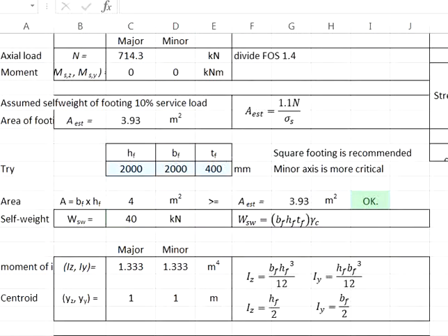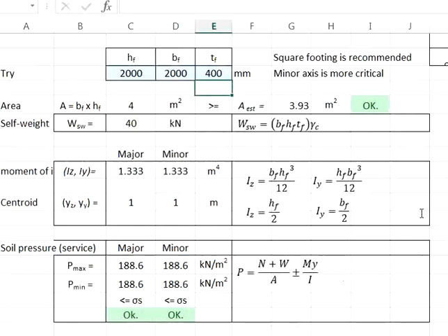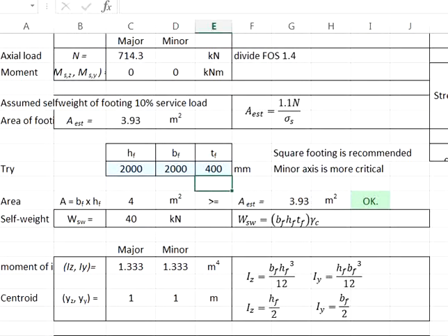Now, if you are doing the manual calculations, you will need to start with proposing a thickness of the pad footing and then go through the tedious calculation steps. If you find the member fails in shear, you will need to increase the thickness of the pad footing. Since the spreadsheet tells that the thickness is insufficient, we shall straight away use 500 for the following explanations. Ultimately, we come to the proposed size of 2 meters times 2 meters times half a meter.